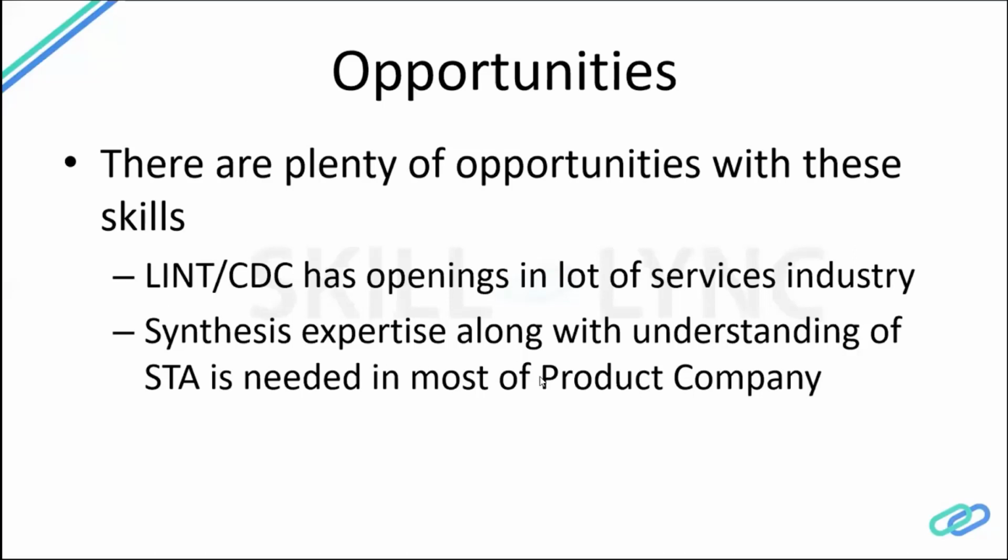Once you go into a product company, you still do lint and CDC, but not that much. If we are lucky enough, we get to work on synthesis and some of the STA, standard timing and static timing analysis. Here we do setup and hold checks in the design, to see whether there are any timing violations in the design.